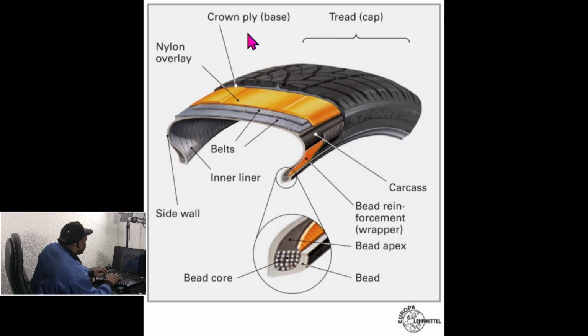Anyway, as of today, tires with inner tube are only used on motorcycles and some commercial vehicles. Tires for tubes, never attempt to use them as tubeless. It is deadly. It can kill, because it was not prepared to be used as tubeless. The one for tubeless is well prepared for the task ahead of it, because they make sure it seals the air by the side. You can see the nylon, that is this yellow one.